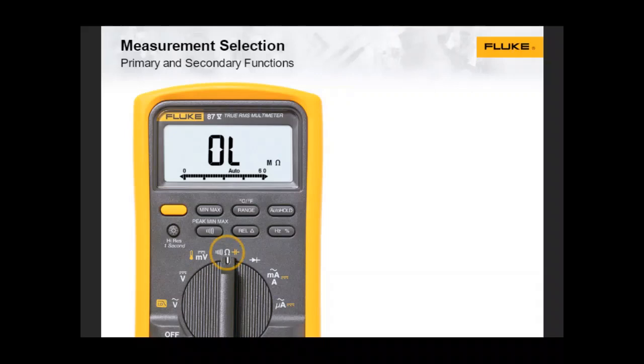For example, to measure capacitance, the selector switch is rotated to the position marked by the capacitor symbol. Since the primary default function is the resistance and continuity measurement, simply press the secondary function button to change to capacitance.